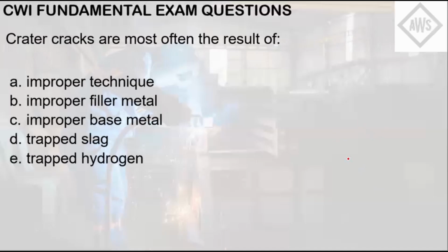So the answer here is letter A. So the improper technique of the welder most often results in crater cracks. As for the choices here, that's why they're not the correct answers: filler metals in base metal do not cause rapid cooling. It depends upon the heat input.